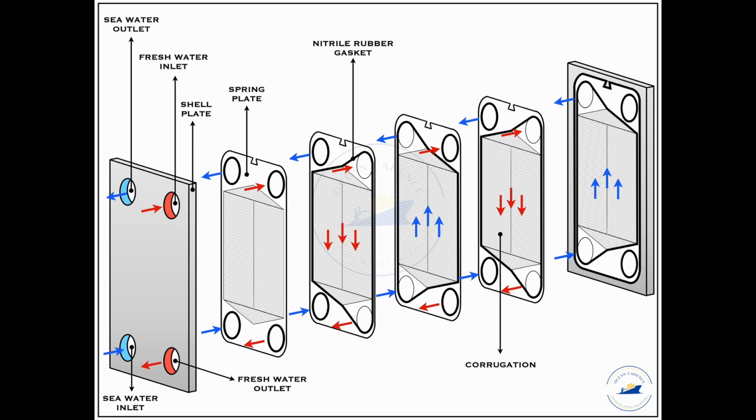Now it is important to know that these gaskets on the edge can have a point where there is a telltale hole assembly. This can either be in every gasket or alternate gasket. Mostly it is available in every gasket to easily figure out where the fluid loss or leak is happening. This telltale hole can also be there in the plate side. Usually a typical arrangement is used for freshwater generator plates, because we know that the feed water of the freshwater plates is arranged in a certain fashion.